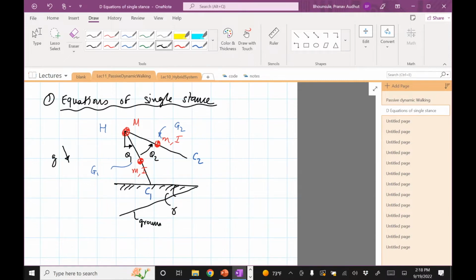When I write the equations, you'll see that the equations are much easier to write, assuming that my world frame is along the ramp and not along the ground. And that can be achieved by just rotating gravity. So gravity here would be G, this would be gamma, so G sine gamma. And this would be G cosine gamma. It just makes my life easy. I can just rotate gravity instead of doing it the other way where I have the axis along the floor.